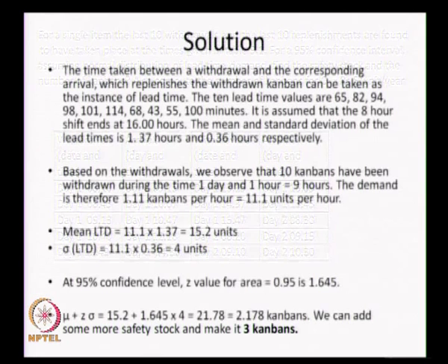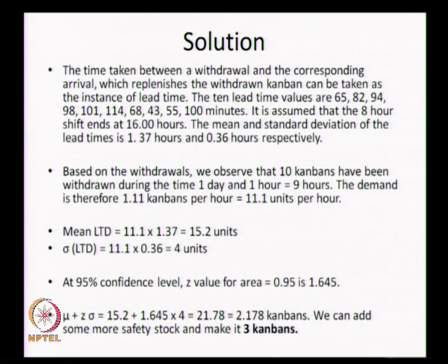So, from the 10 withdrawals and 10 arrivals, the time taken between a withdrawal and the corresponding arrival which replenishes the withdrawn Kanban is taken as an instance of a lead time. So, the 10 lead time values calculated are 65, 82, etc. and the 8-hour shift ends at 1600 hours. The mean and standard deviation of the lead times calculated from these 10 values are 1.37 hours and 0.36 hours.